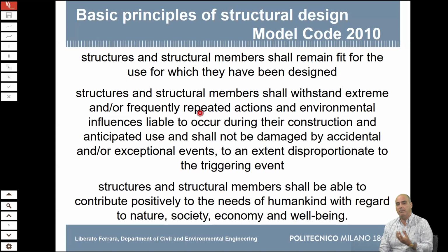But can you imagine you are designing for gravity load, for live loads and so on, and then you design for earthquake? Can you apply the same design philosophy to the two cases? Because when you design for an accidental action or an extreme event like earthquake, you cannot require that the structure performs in the same way as under your gravity and live loads.